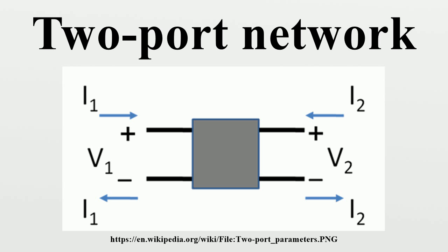This difficulty can be overcome by placing one-to-one ideal transformers on the outputs of the problem two ports. This does not change the parameters of the two ports, but does ensure that they will continue to meet the port condition when interconnected. An example of this problem is shown for series connections in figures 11 and 12 below. Series connection: when two ports are connected in a series configuration as shown in figure 10, the best choice of two-port parameter is the Z parameters. The Z parameters of the combined network are found by matrix addition of the two individual Z parameter matrices.